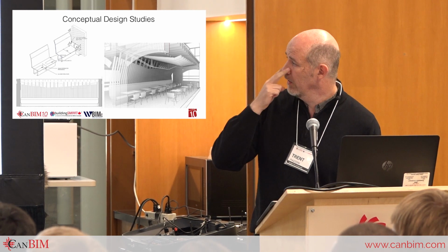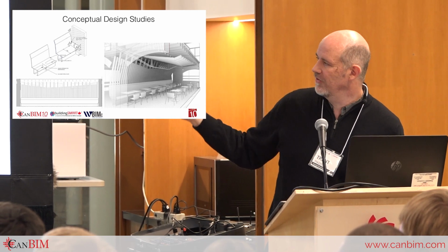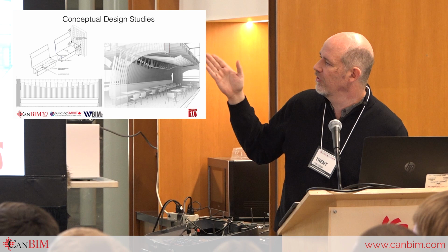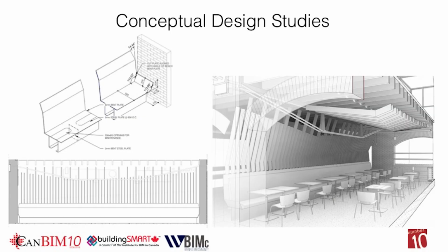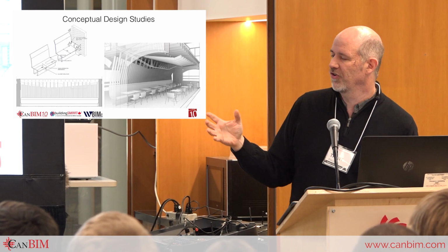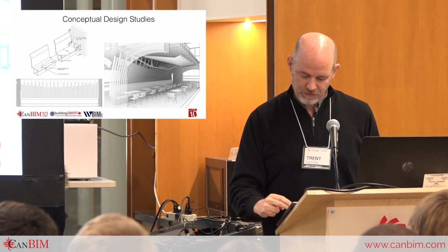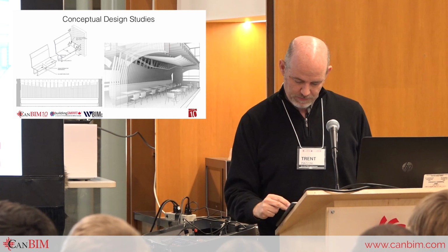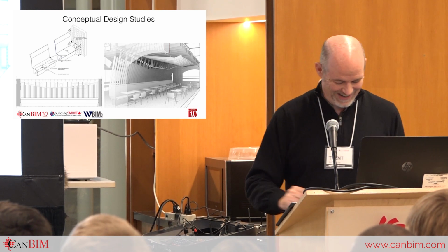And then we also were worried about the quality control of the stud spacing made in existing space. So what we ended up doing to control that was laser cut holes. It's a steel bench that we cut holes on center to do quality control again. We get a lot more precision with laser cutting. And we went from there. Let's make some consistency. I think that was everything on that.